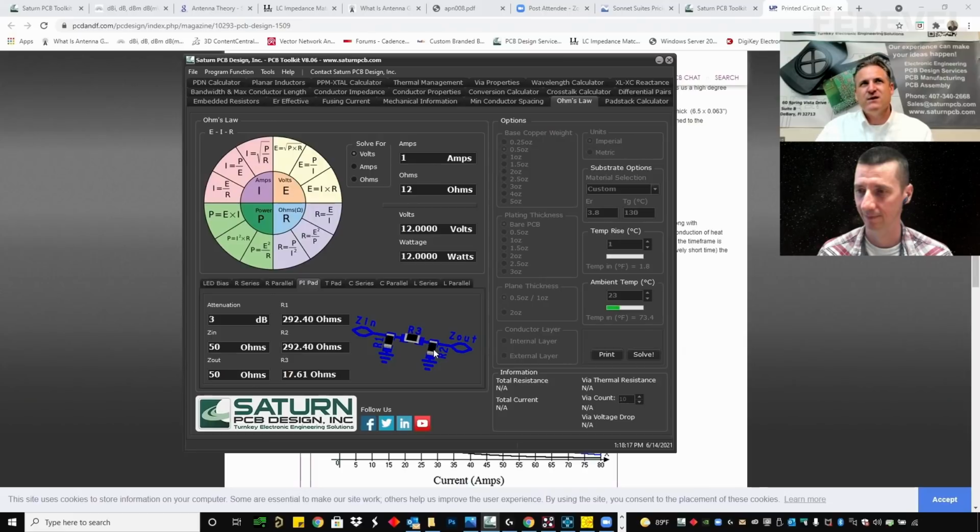It happens a lot of times if your receiver signal is really high and you want to knock it down because it might burn up the input of your LNA or something like that, and I want to add 10 dB of attenuation to my receiver, here's the values in that configuration of resistors that I need to knock me down 10 decibels. Same with the T-pad.